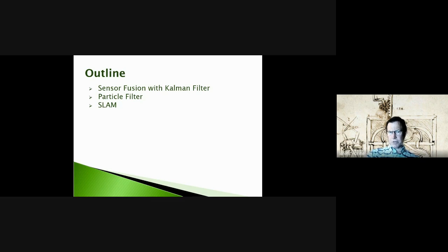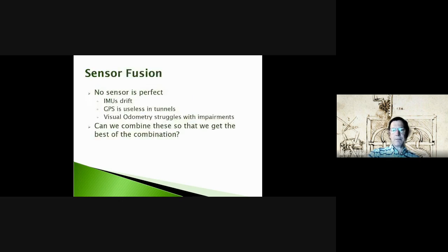A particle filter requires you to have a map already that you can match yourself to, figuring out where you are by comparing what you would expect to get given that map and a particular location to what you're actually getting. But sometimes you don't have a map, so we could build one up as we go, hunting around and using the simultaneous localization and mapping approach.